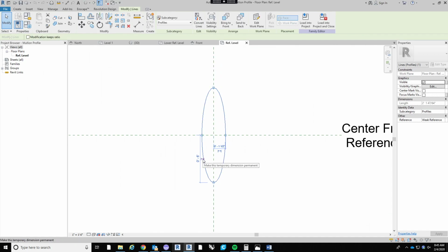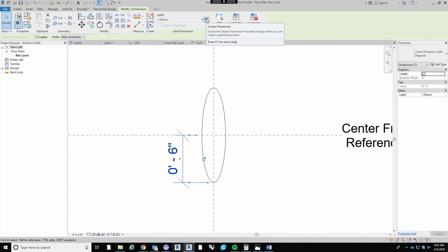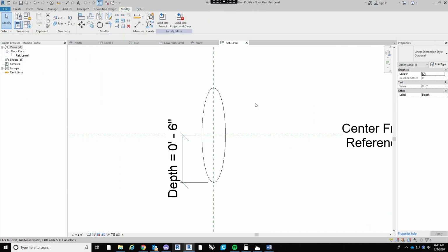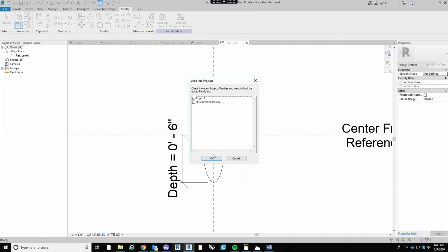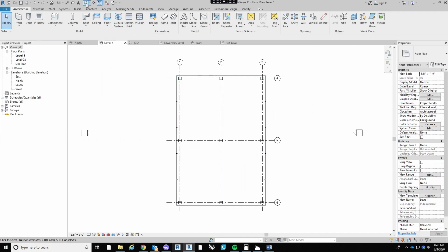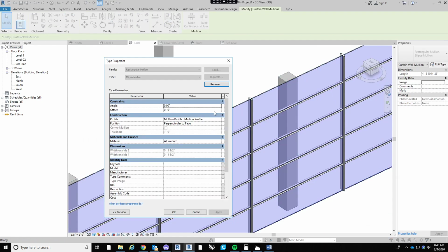So if we hit that dimension, make that permanent, drag that guy out, and then go and create a parameter under create parameter. Depth. Press OK. Now we can load that back into the project. Always overwrite the existing. And then if we go into that mullion, edit type, now our depth will...